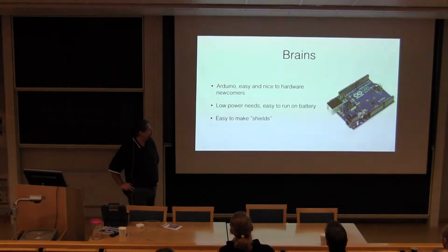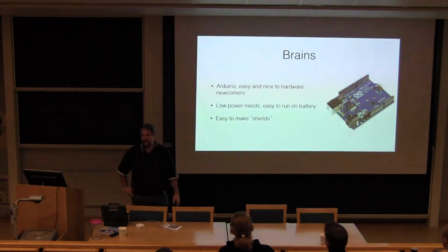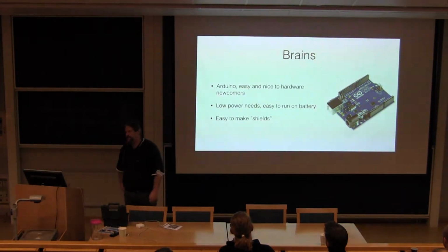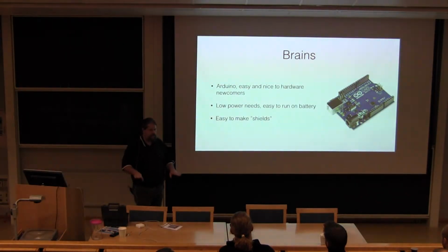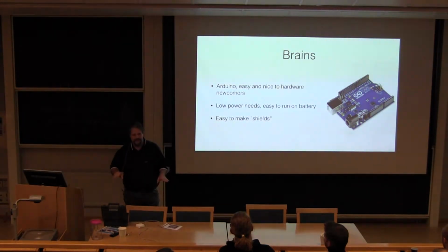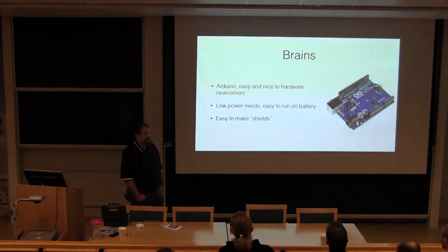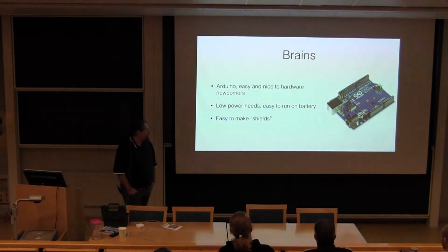The other thing is this is a 5 volt system, and most of these easy electronics are actually 5 volt. 3.3 volts is much harder to actually do. You do have to make boards and use surface mounted circuits. Surface mount, or much smaller, and that's much harder for a beginner to actually work with. So it fits well for a beginner to start here.